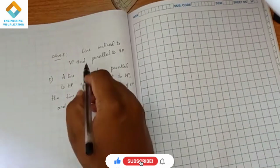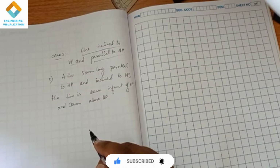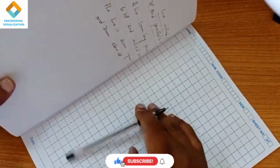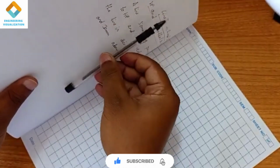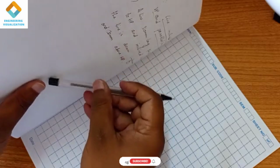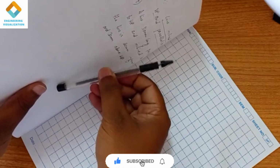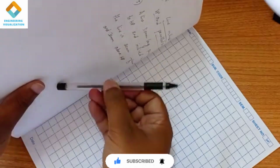The fourth case, that is line inclined to VP and parallel to HP. So how is it? You can see this is our VP plane, this is the HP plane. Here you can see this is parallel to HP and parallel to VP. Here we are giving inclination, whatever the inclination is, we will give it like this. So this is the inclination to VP, and it is parallel to HP. Like this we have to do it.